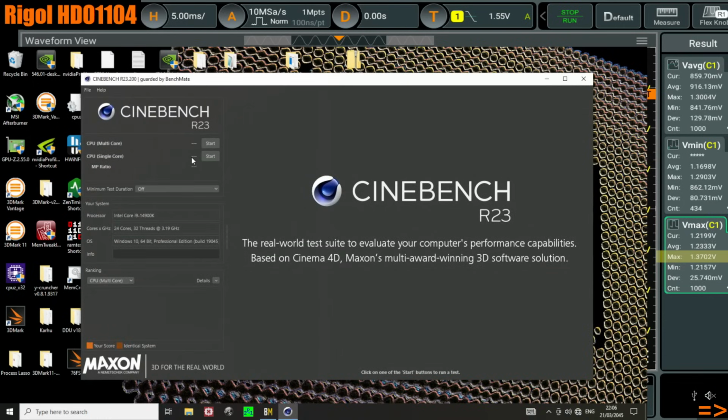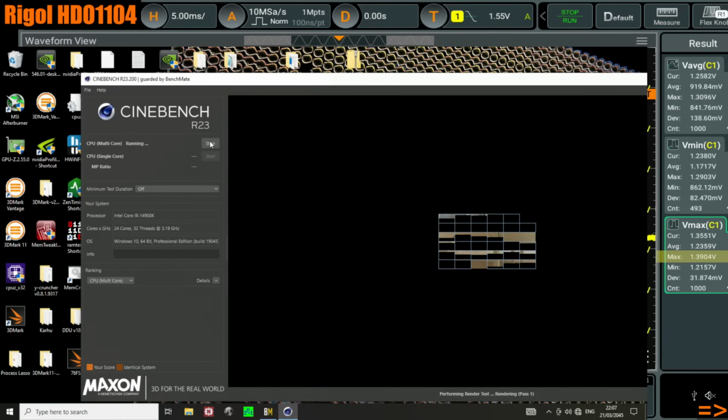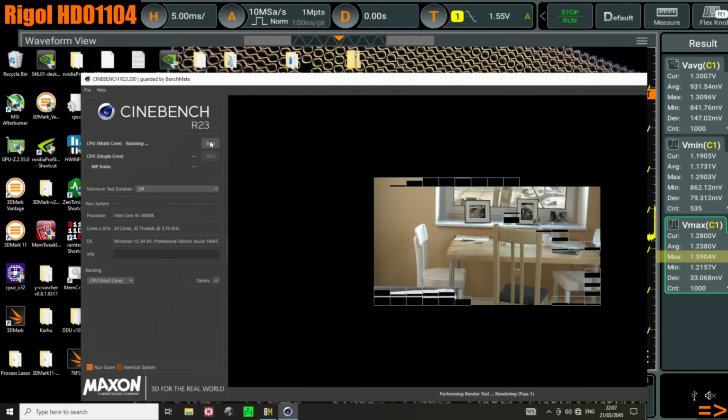Intel doesn't have exactly the world's most granular boost algorithm, but you have 6 gigahertz, 5.9, 5.8, right? So it goes in 100 megahertz steps. Just between 5 gigahertz and 6 gigahertz, you have about 10 different frequency-voltage combinations. And if one of those isn't stable in one application, it's going to crash, or it's just going to be really weird. That's the main concern with undervolting: stability testing is really, really, really frustrating.